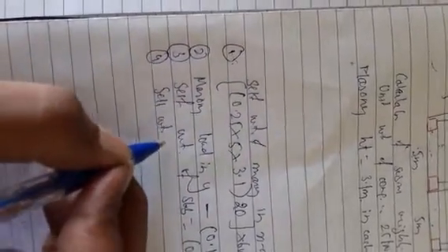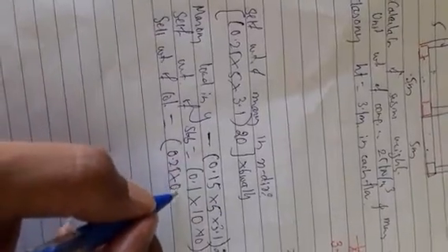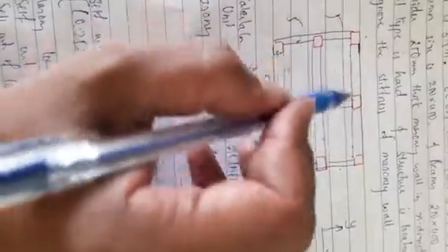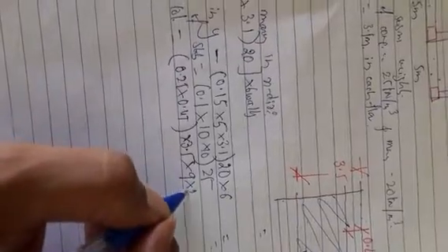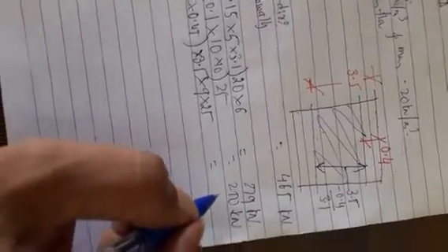Now fourth, self weight of beams. Or let me first columns. So column size B into D 0.25 into 0.45. It is given in the problem. Now height of the column is 3.5 meters. It is extending from here till here. So whole height you have to consider, 3.5 into number of columns 1 2 3 4 5 6 7 8 9, into 9. Its unit weight 25. So you get the answer for the columns 88.6 kilonewtons.